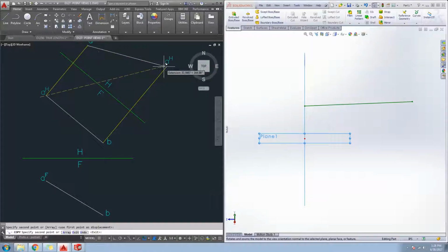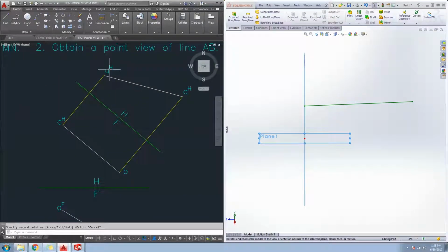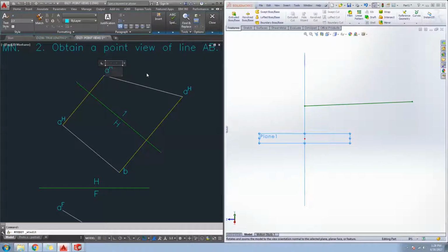Okay, there. We'll need to make sure that our identifier for this folding line is correct. These letters should match. This is both the horizontal plane. This should be auxiliary view 1. So that right there should be a superscript 1.